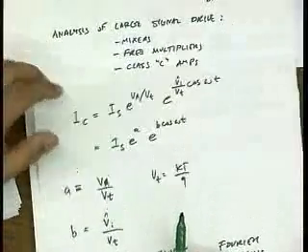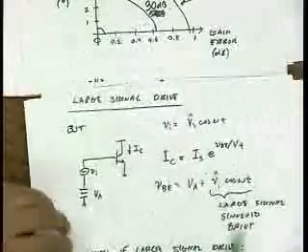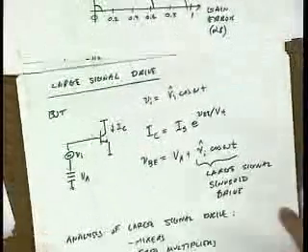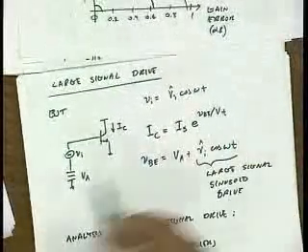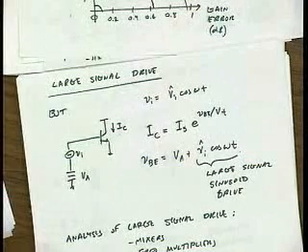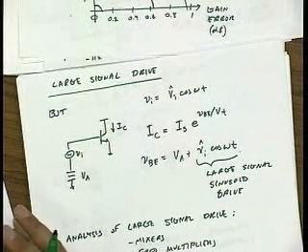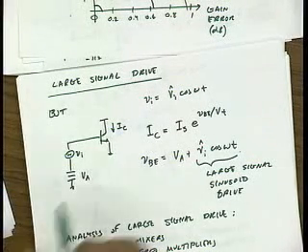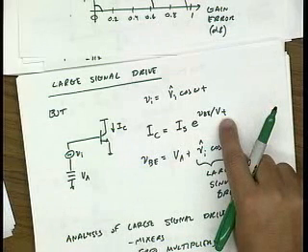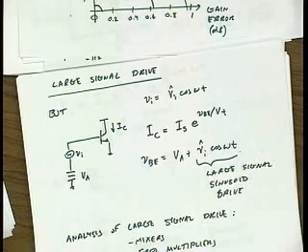So if we go back here and look, if I wanted to use a power series expansion, I would just take this exponential and do a power series on it, right? That's what we did earlier in the lecture. But the signal would have to be relatively small relative to Vt for the power series expansion to be valid, right? Otherwise, I'd have to carry 100 terms.